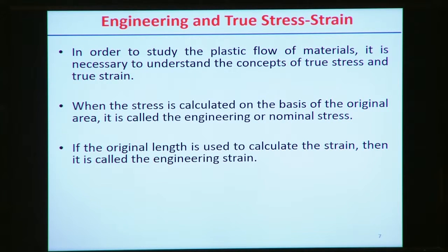When stress or strain is calculated based on the original cross-sectional area or initial length, that is the engineering stress or strain, also called the nominal stress or strain.